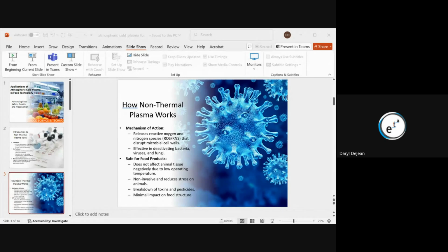Most other types of treatment, and I'm talking about the one that's most effective here, are called non-thermal plasma because they don't have accelerated high temperatures. What they do is they agglomerate. They attach to the pathogen to make it bigger so it gets caught in the filter. So they are not deactivating the pathogen. They're simply attaching to it, taking it for a ride through the air system till it gets to the filter. That's a very critical thing to remember.